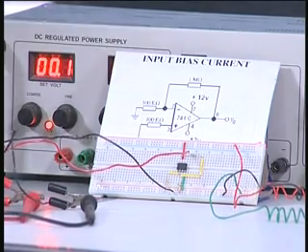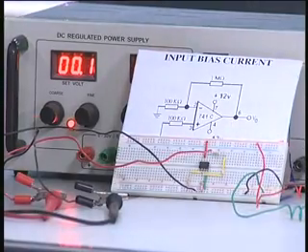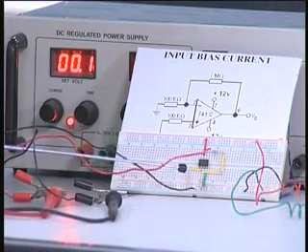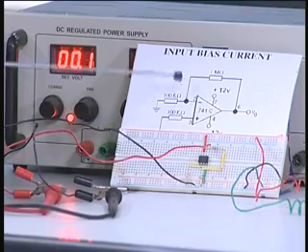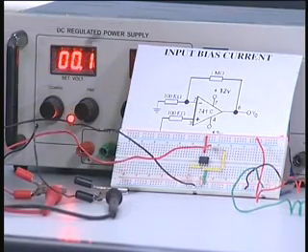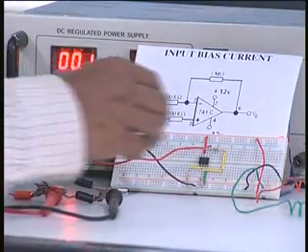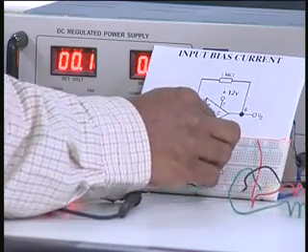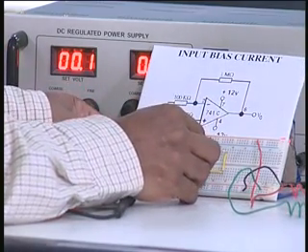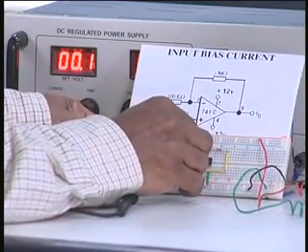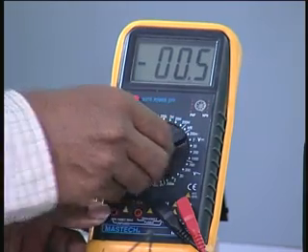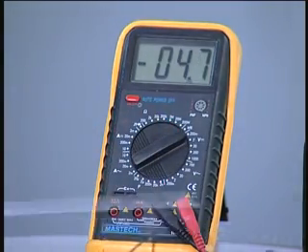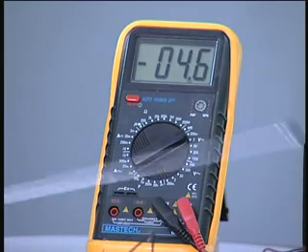So you can see the corresponding op amp circuit is shown below in the breadboard. You have the op amp and the different resistors are connected exactly in the same manner shown here, and now what I am going to do is take the multimeter output and connect it to pin number 2 and measure the voltage at pin number 2.